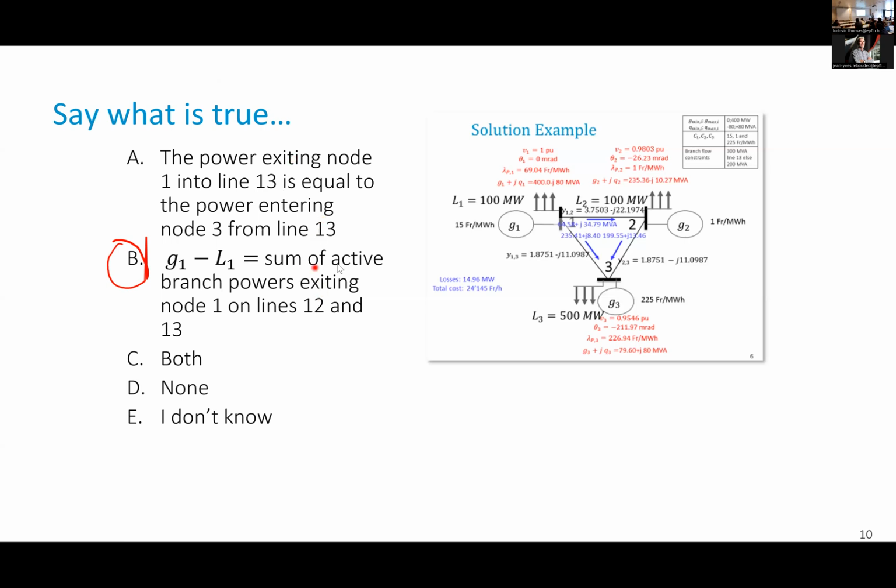No, that's exactly true. So the active power, the loss is on the line here, is not here. So the active power that goes here and there is equal to the active power that's injected by G1 minus the active power that's consumed by L1. And then you don't account for the losses afterwards. No, but the losses are in the active power. G1 is injected more on this line than is received at the other end. Isn't the slack loss designed to take into account also power losses that we'll have afterwards?